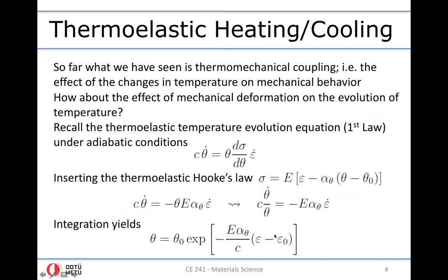So far, what we have seen is the effect of the temperature on the mechanical response. But what we would like to also explain is what we have seen in the first slides. In other words, what happens under adiabatic conditions if I deform the bar at a very fast rate of deformation in tension and compression, to see whether this constitutive relationship, the simple extension of Hooke's law, can explain thermoelastic cooling and heating, respectively, in tension and compression.